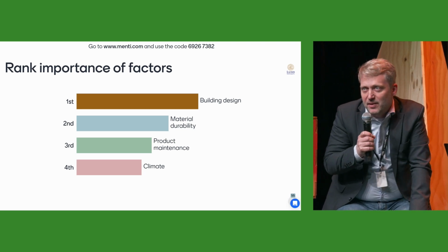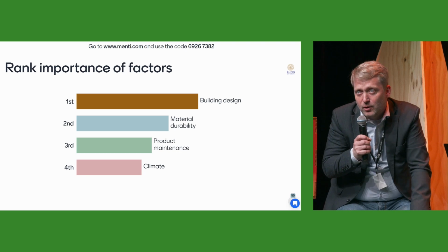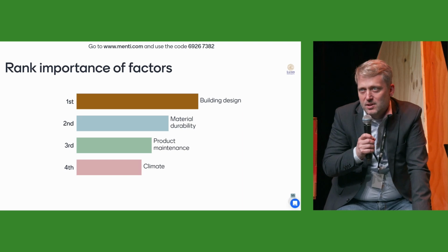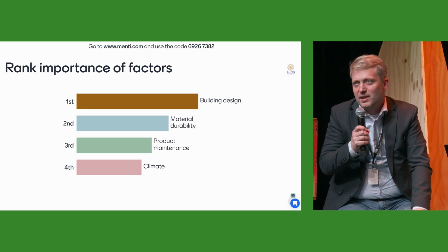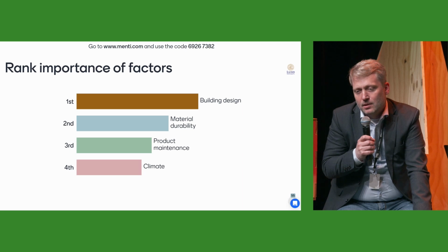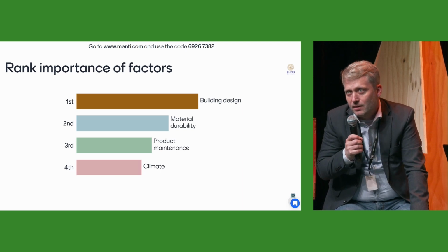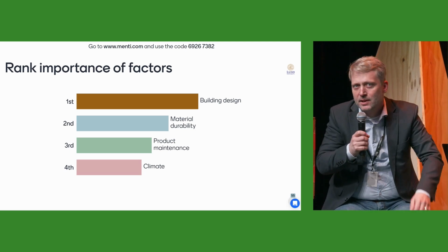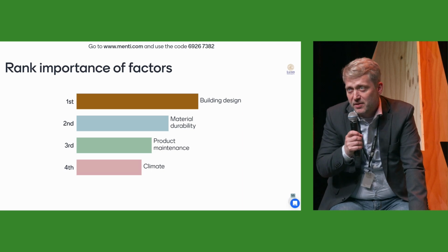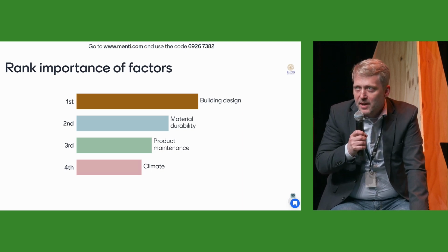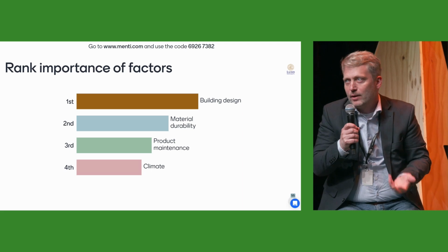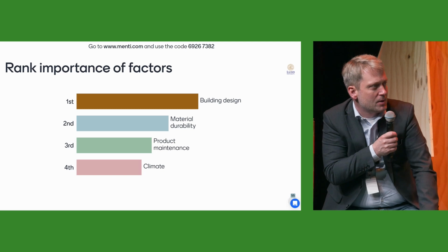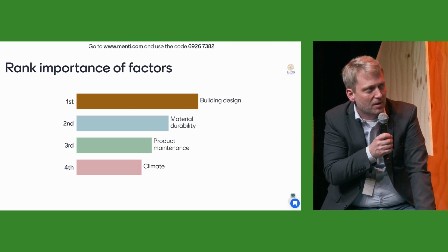If there is not enough moisture because you have a proper design with a lot of shelter for your cladding, for instance, then of course the dose and the risk for decay is 0. With material durability, of course, you can reach quite a high resistance when using heavy-duty preservatives, for instance, but it will always stay a biodegradable material. It will just take longer, but it's not a KO criterion. So that's maybe the important thing here.